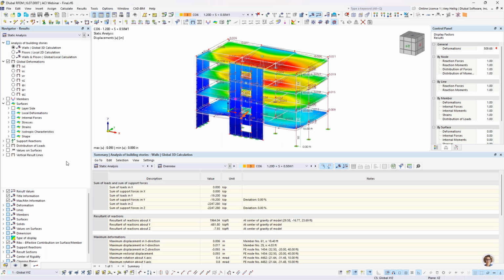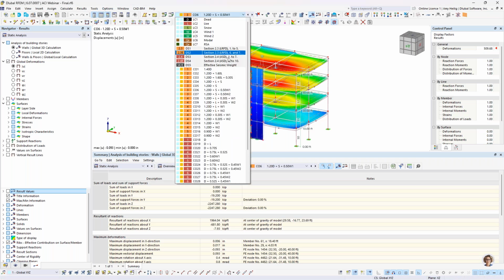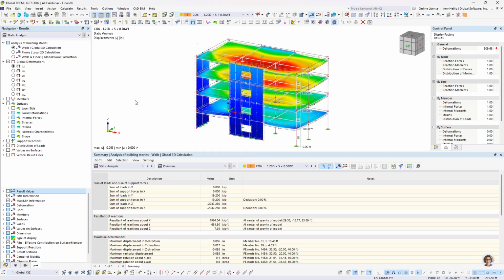And you'll notice that because I have defined that semi-rigid diaphragm, or if we had defined a rigid diaphragm, we have the additional settings up here under the static analysis results, including that 3D calculation. So again, we're calculating in a 3D environment, all elements are considered. We're running through all of these load combinations here, both gravity and lateral loads. We're just going to modify the diaphragm stiffness for this global calculation. In turn, we can toggle here to that local